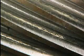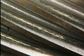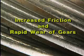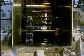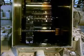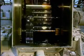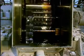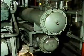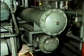The use of the wrong type of oil or grease for a gear set results in increased friction and rapid wear of the gears. Heat can cause problems for gears when a lubricant does not remove the heat quickly enough. Heat damage can cause gears and gearboxes to distort, which can result in severe misalignment and damage. Overheating could be caused by a loss of cooling water flow to an oil cooler.